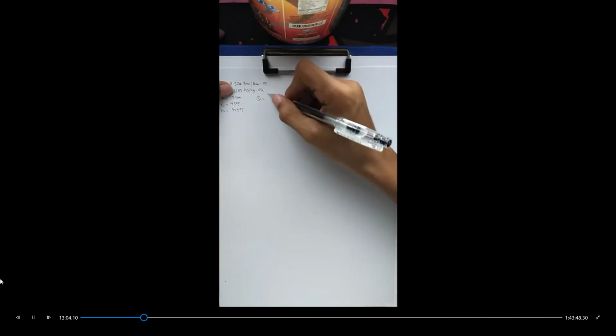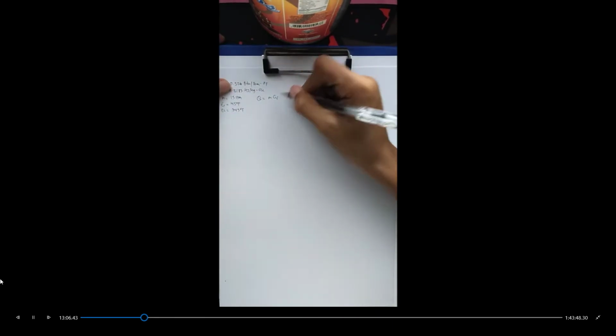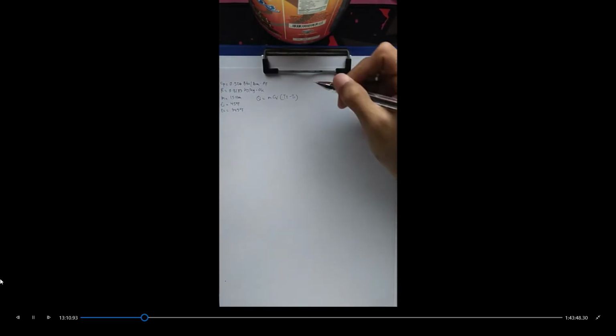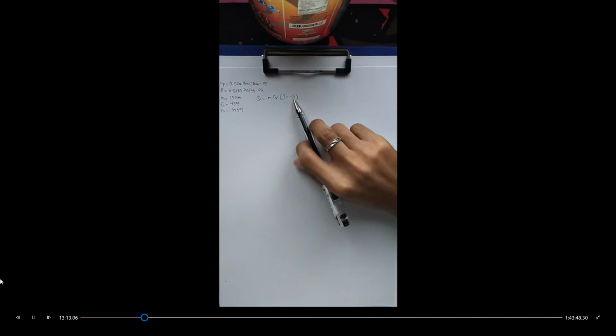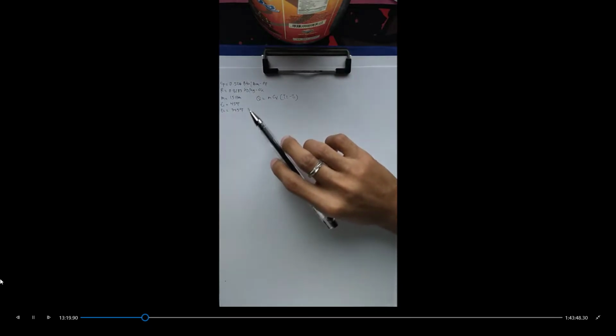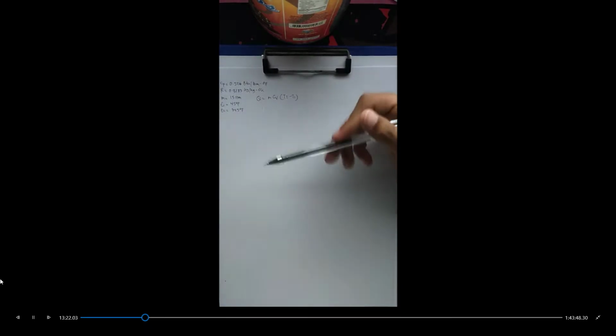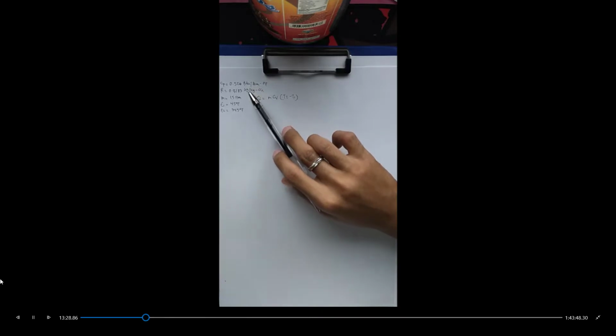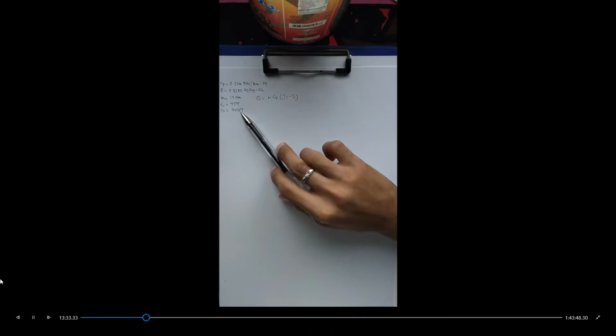The general equation for Q at a constant volume is mass, constant volume specific heat multiplied by the change in temperature. And the change of temperature needs to be in absolute form. We need to convert these temperatures into absolute form. And if you're going to look at the units, our constant pressure specific heat is in English system, our gas constant is in metric system, our mass is in English, our temperatures are in English system.